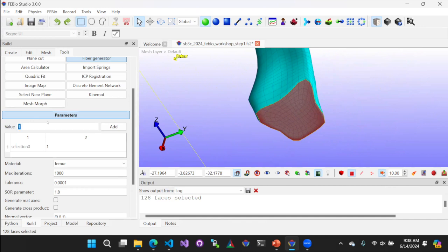Okay, so for this, we'll give it a temperature value of 0. It doesn't really matter what value you give it as long as it's not a 1, because we have already used 1. So we want to create a temperature distribution, so you can use 0, you can use 2, you can use whatever you want. Just don't use 1. Okay, so we're almost ready.